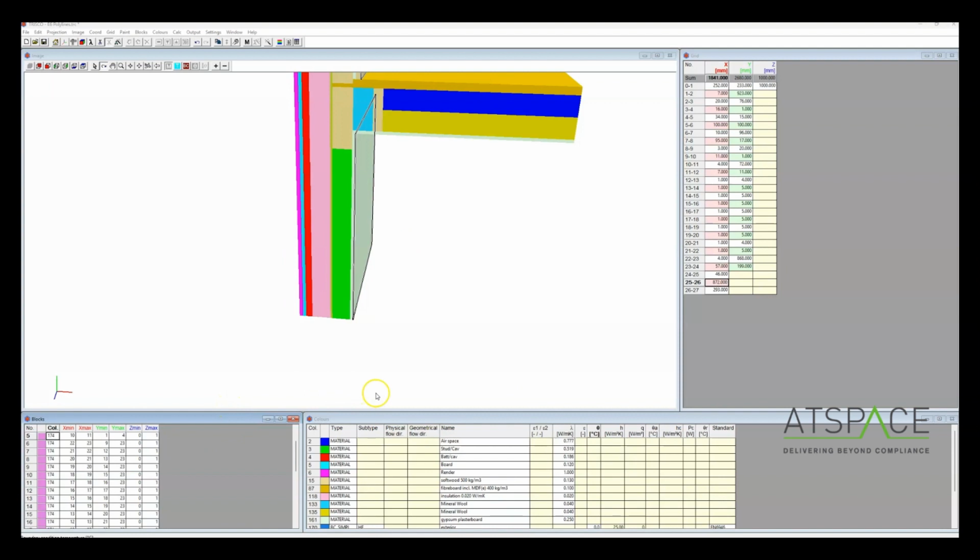So I've gone through all my list of colours now, and got them all set up how they should be. All the conductivities are correct now, and I've renamed them all to represent the materials. So the next stage now is to go to grid up here. It's currently at the minimum grid, which means that it's just set to have the minimum required grid to fit in the blocks that are in the model.